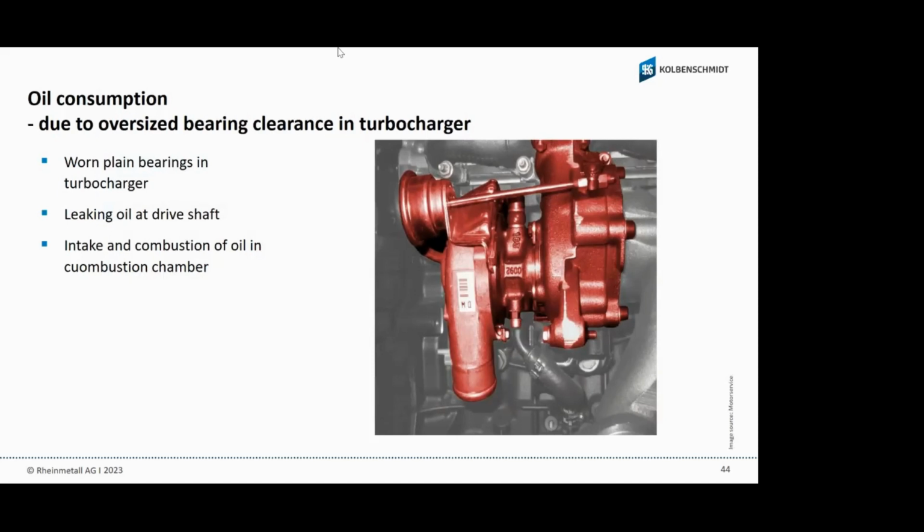This is also a big problem with engines with a start-stop system. When they stop the engine while the turbocharger is very hot, they burn the oil on the wheel and bearing side, and then we have a lot of wear because of the carbon that built up there. This is also why the manuals say, when you come from the highway or when the engine was under very high load, please let the engine run maybe 5 minutes at idle speed. That cools down the oil and the turbocharger, and then you stop it.